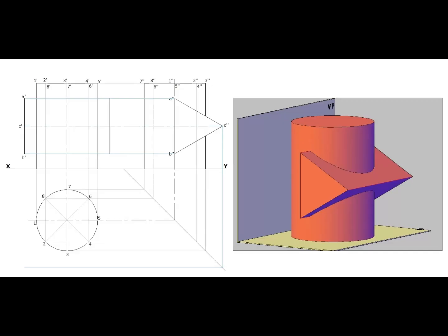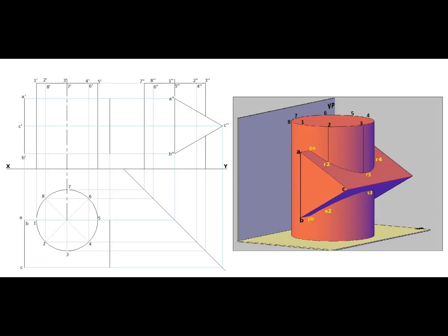Project those points vertically up to the miter line, then horizontally to draw the plan. The elevation also can be projected to maintain the length in the plan. Name the corresponding edges of the plan as A, B, and C. Now we have to trace the points on the curve of intersection. Before that, the edges of side view and plan can be drawn dark.